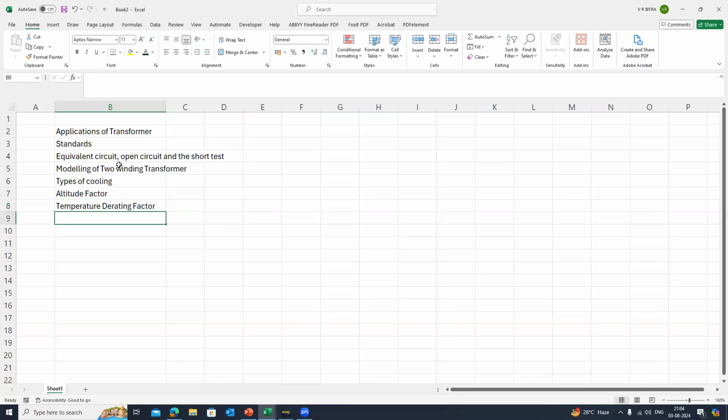And then we will discuss the impedance and its tolerances allowed for the transformer as per the IEC 60076 part 5. And then at the last, we will see the OLTC range, meaning how to select the OLTC ranges, on-load tap changer, whether it may be the fixed step or with the help of the AVR, the automatic voltage regulator, and how to do the tap optimization.